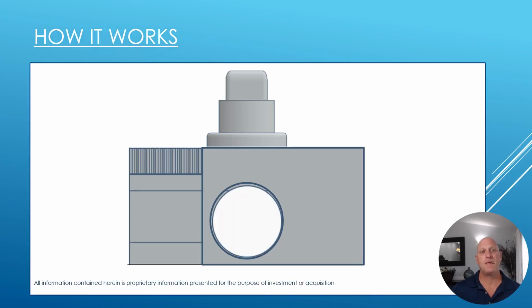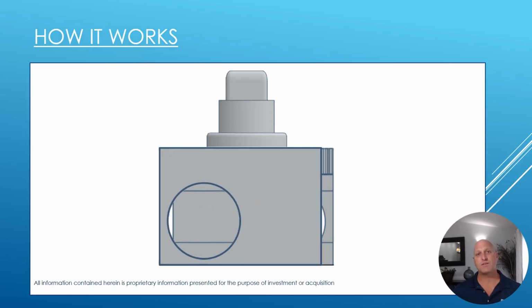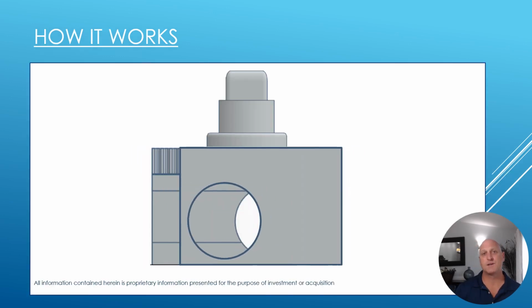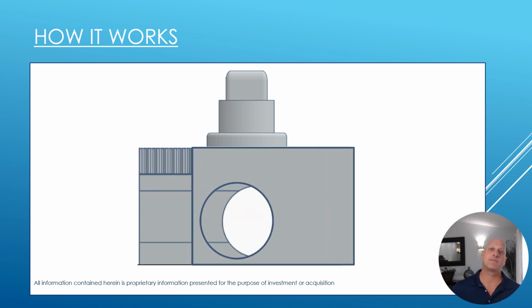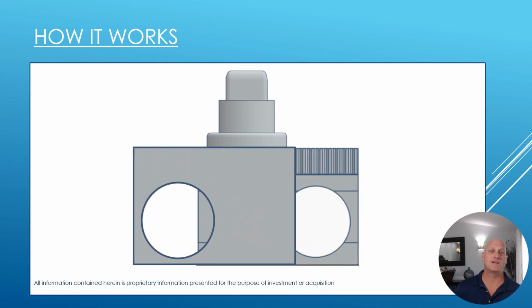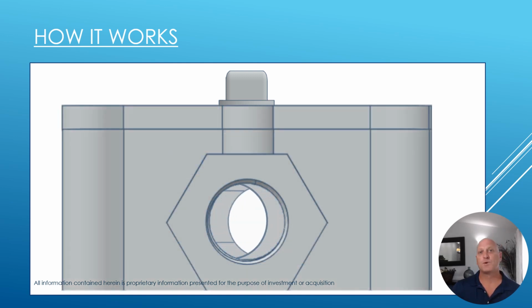To be able to shut off more positively. If I'm looking at it from the front, this is how the 2 plates slide. You can see it works very similarly to a cigar cutter. In fact, that was the inspiration for it. I just wanted to adapt that kind of simple mechanism to a 90-degree actuation. And if we're looking at it with the body of the valve on there, you can see again how we're directing the flow towards the center of the path.